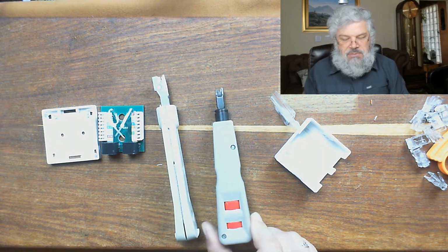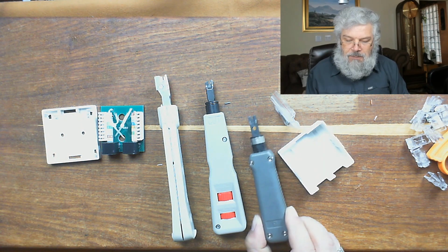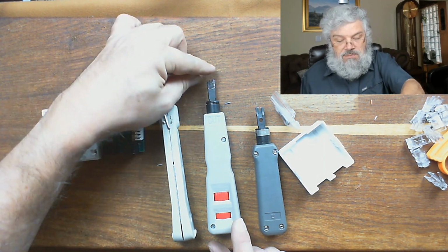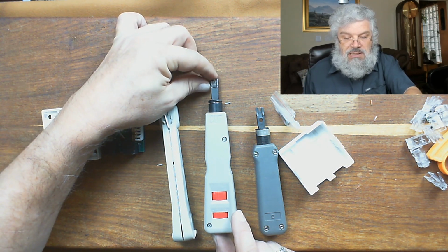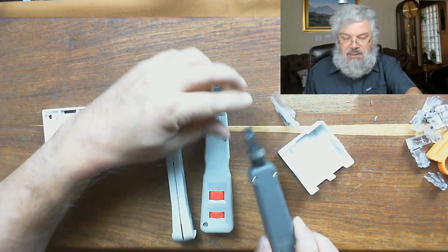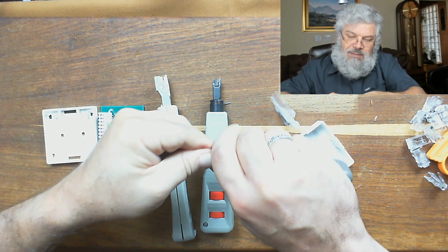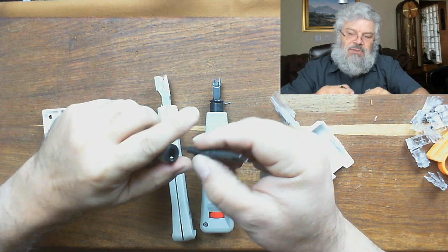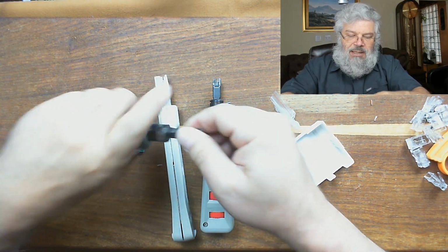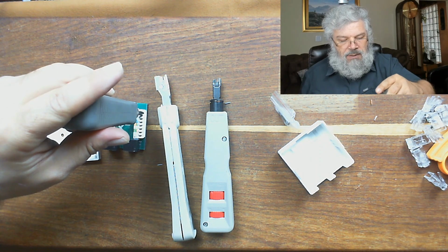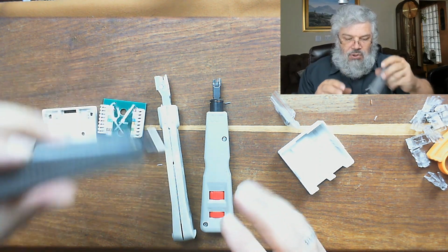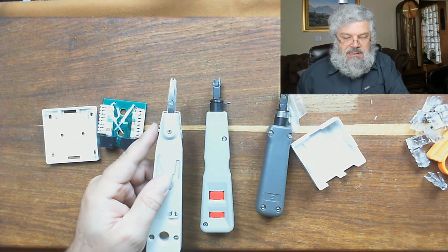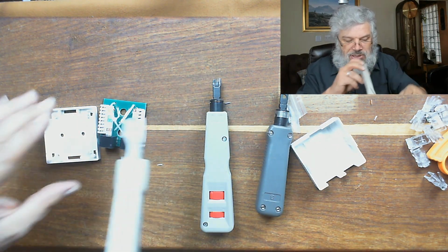They will look something like this, and one of the things to be very careful of when you use these punch down tools is that some of them have sharp edges. In fact, on most of them you can interchange them, so that you do get the sharp edge, and then as you are punching down, it can cut the wire on your behalf. This one's got a nice little scissor there that will cut the wire as you're punching down.